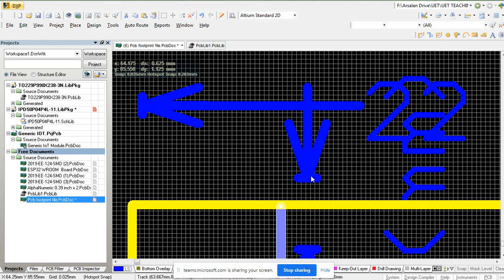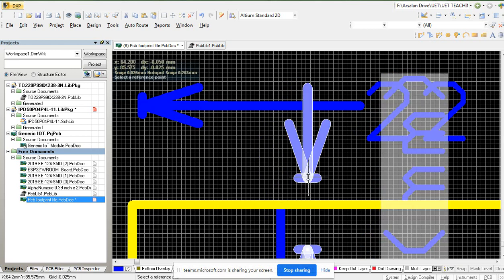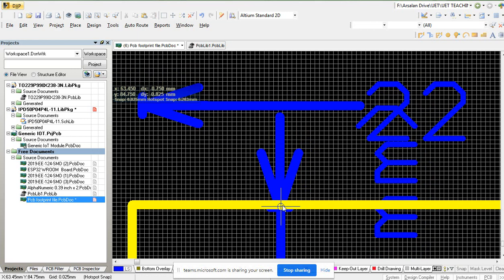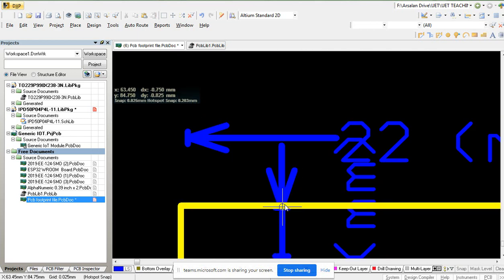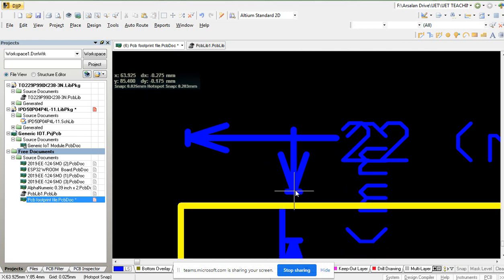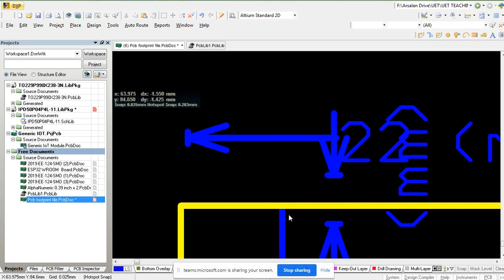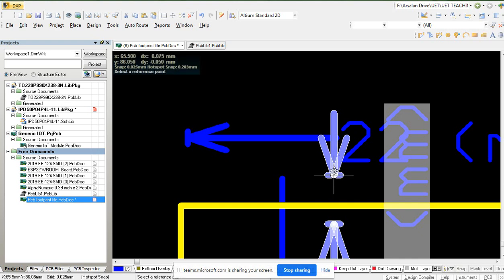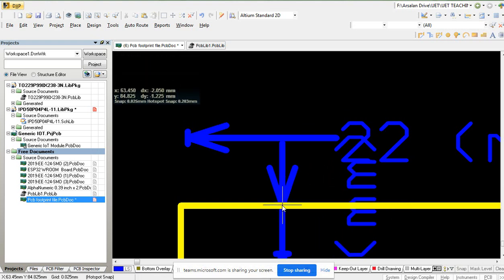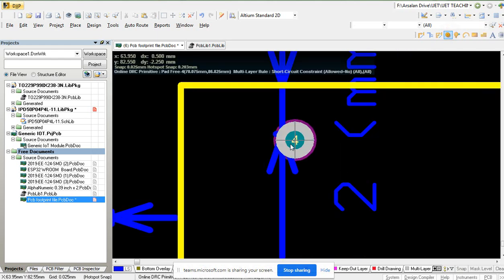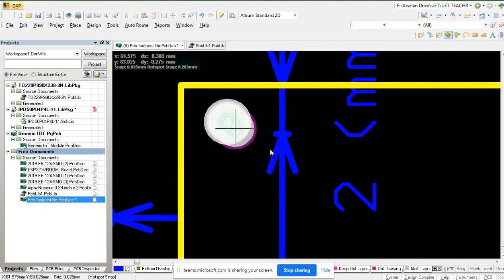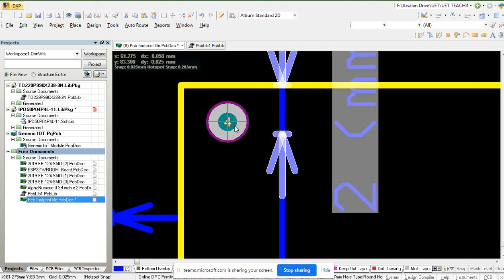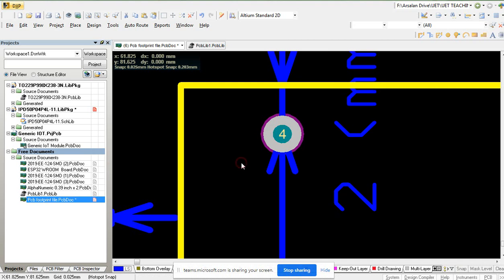Okay, this one is a little draggy. Sometimes the software, actually I will just make it a little above, and now this is going to work over here. So you can see just the center of this track, and now I can place the pad easily. Please always select it, so when you are dragging the pad, it's exactly at the center.